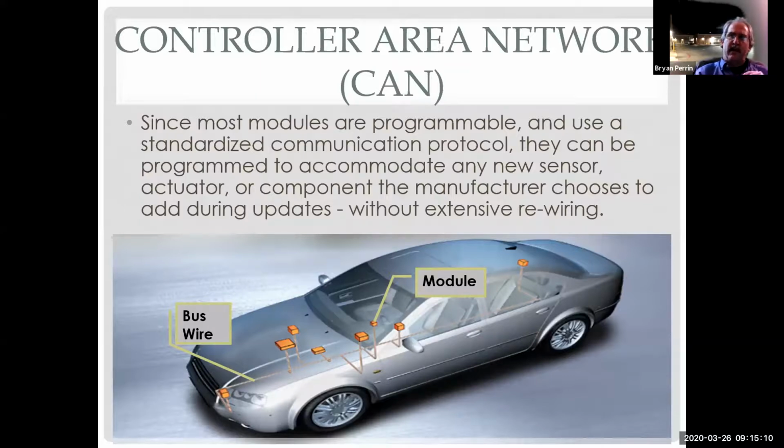So it allows them to, instead of making 5 or 10 different wiring harnesses, depending on how the vehicle is going to be equipped, order one wiring harness. The same car gets the same wiring harness, which means the colors are much more consistent. The wiring and the connectors are more consistent. The vehicle makes it easier to diagnose.